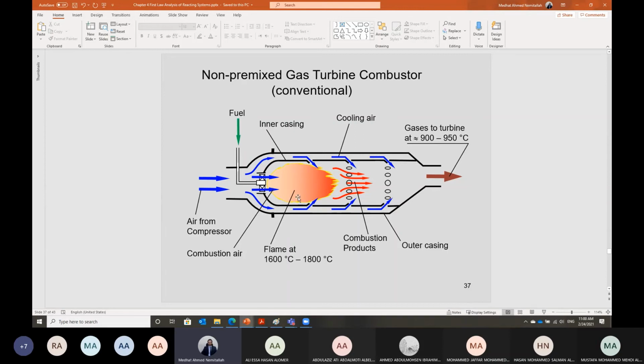And that's why, shabab, there is a stoichiometric combustion zone. They are created in this kind of flame, and the combustion temperature in this case will be very high. Combustion temperature very high means we have dissociation of nitrogen, and that means we have higher emission of NOx in this case.